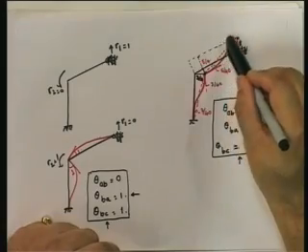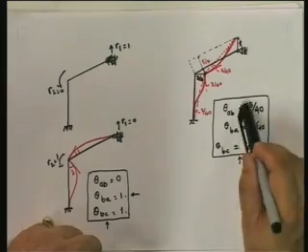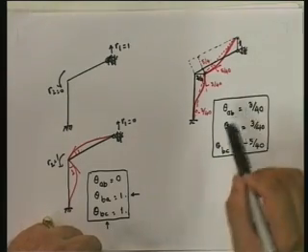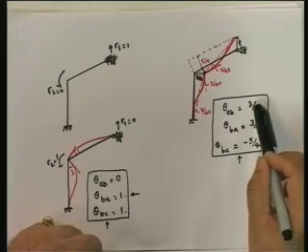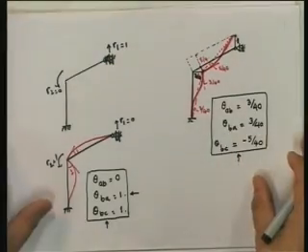Okay, so the point that I would like to make is that the kinematics definitely depends on the support conditions. However, if we change a fixed support condition to a hinge support condition and keep the geometry the same, it has no effect on the overall kinematics. Of course, as I said, the displaced shape may look different, because if it was fixed, it looks like this and it would look like this. However, as far as the kinematics is concerned, that is the relationship of the member end rotations with the degrees of freedom of the structure, they are no different from what we had evaluated last time.